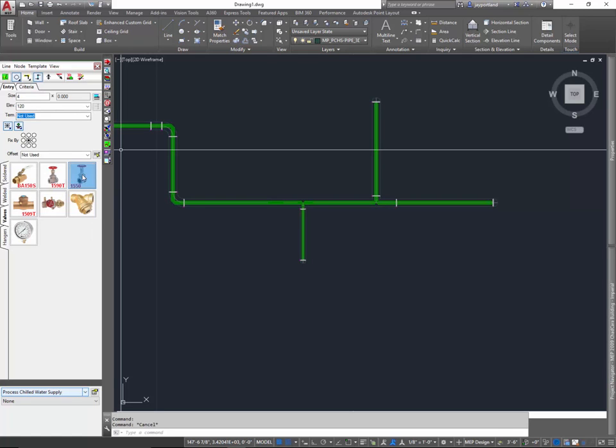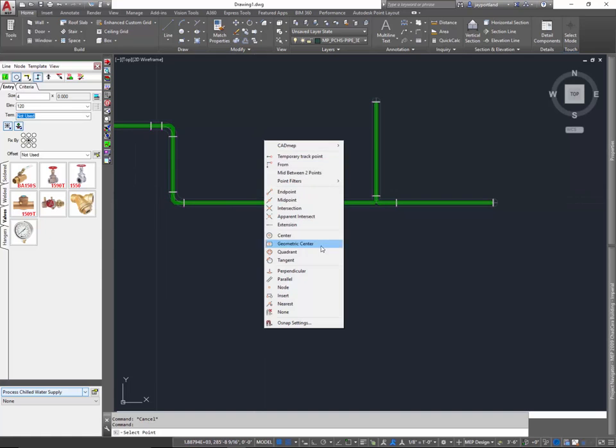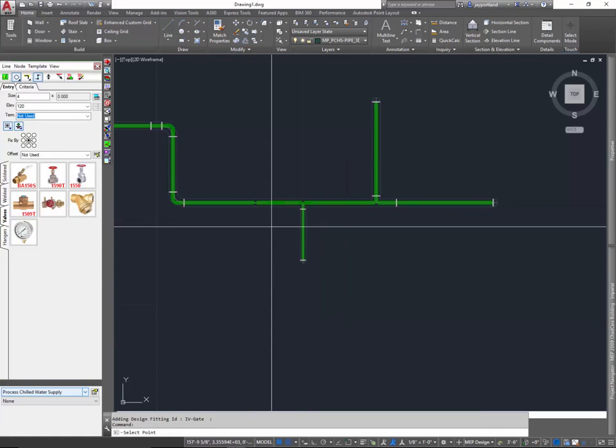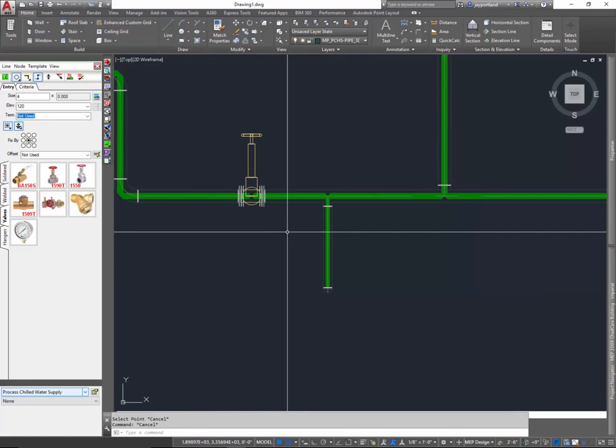And let me place another valve here, so I'll go ahead and add the valve. And this time, using the design line, it's a little bit different because you'll just go ahead and pick on the design line where you need it to be. So I'll pick right here. And you'll see that the design line has a new location in there, but there's no valve that appeared. And it won't appear until you go through and reformat the 3D graphics here.